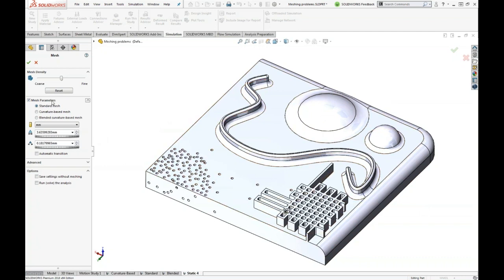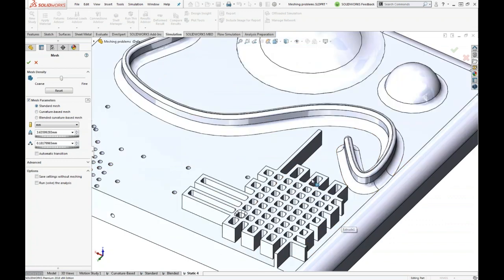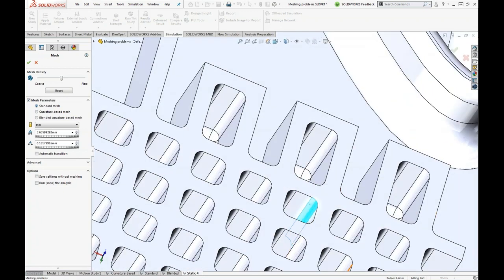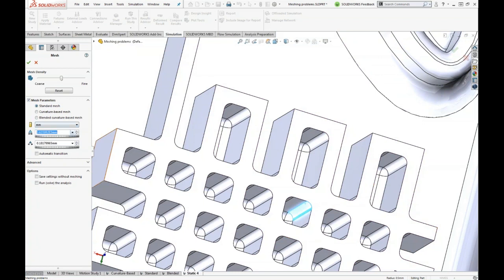Okay. The standard mesher, in essence, is going to look at every single face in the model, right? So that's a face, for example, and try and map a 3.64 millimeter element to it. If that face, well, in this case, this has a radius of 0.5 millimeter, that face can't fit that element, it'll try and skew it within a tolerance.